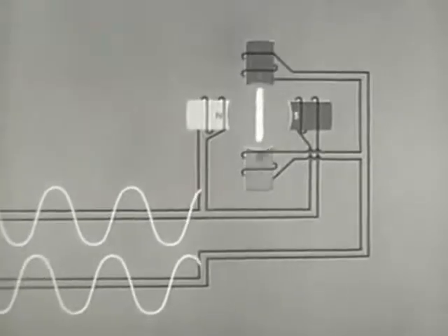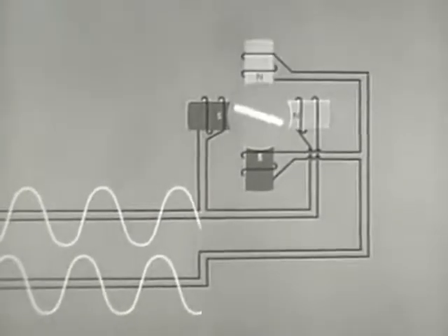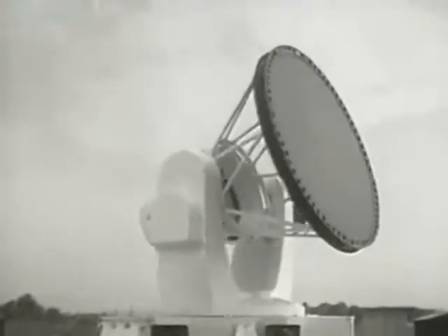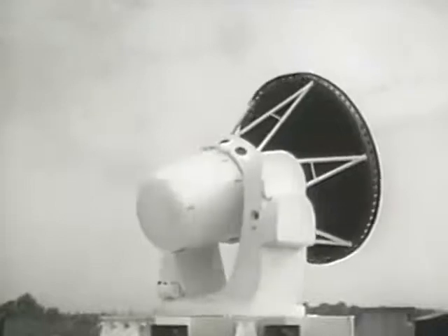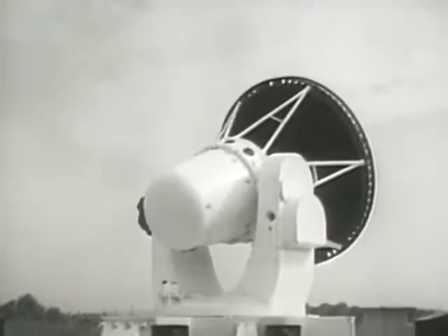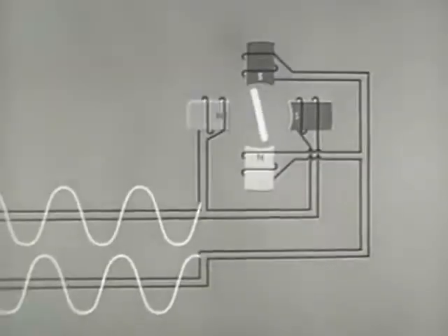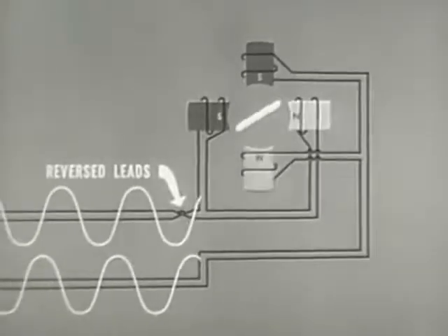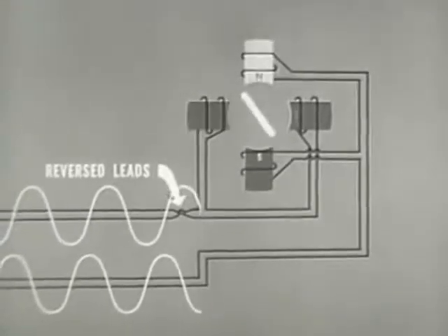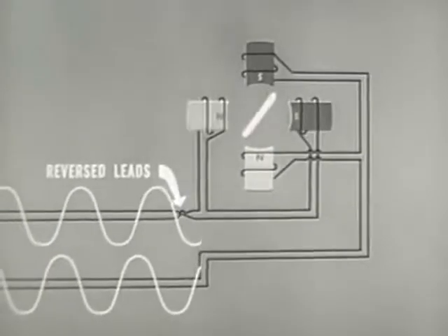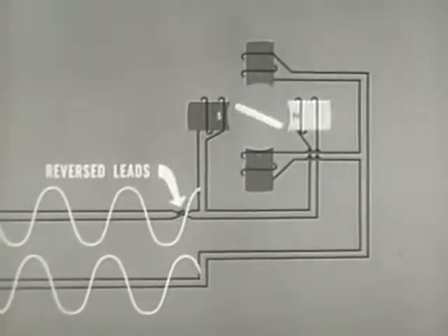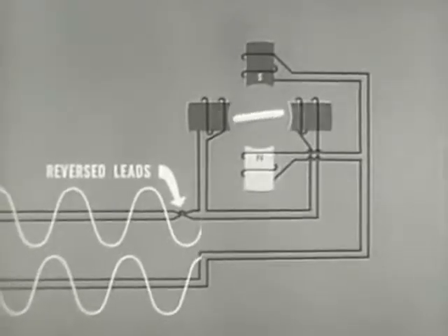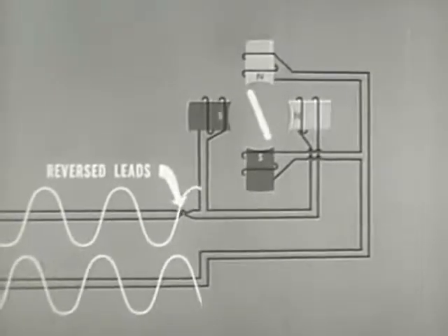Again, the rotor turns in the same direction as the magnetic field, but at a slightly slower speed. The two-phase motor in this installation is called on to change its direction rapidly. This rapid change of direction is accomplished simply by reversing the polarity of only one set of poles in the motor. The polarity of the second set of poles will remain unreversed. The field will now rotate in the opposite direction, with the rotor following at a slightly slower speed.